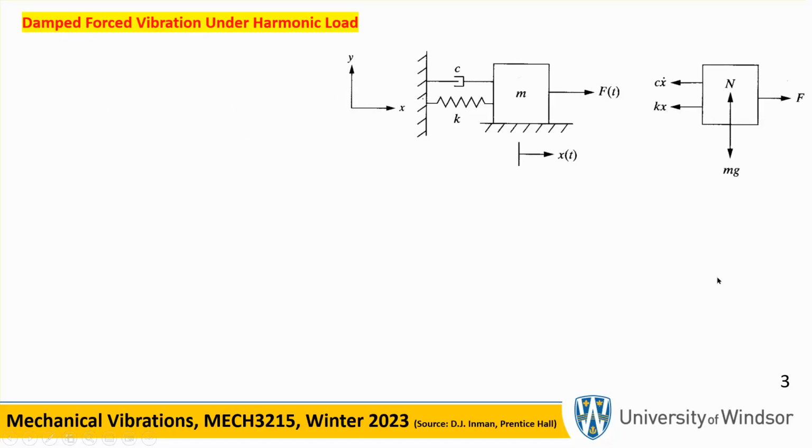All right, so we have a damped vibrating system, so a mass spring damper system, and it's subjected to a load F of t. That's why we say it's a forced vibration, okay? But the load F of t is of a very special type. It's a cosine type, so it changes in a sinusoidal manner as a function of time. So it's effectively F naught cosine of omega t. This is the mother of all equations. Instead of being 0, which is the first 3 weeks of the course, it's forced: F naught cosine omega t.